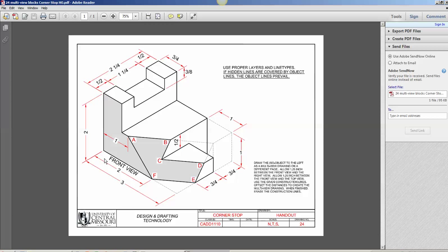Okay, and then from this corner to point F is 2, so we should be able to draw line AF in front view. Okay, and then we continue. So from here we go up 0.5, we go to left 1, go up 0.5 and connect to point A.